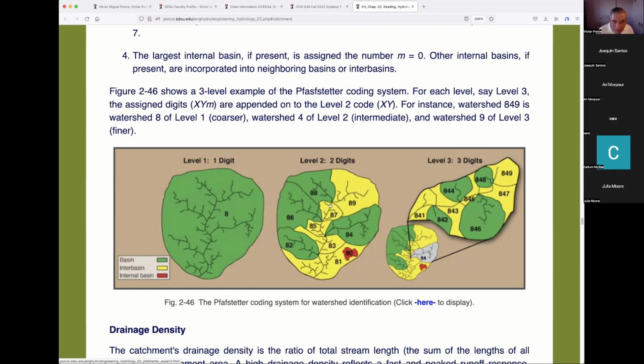Then the intervening reaches of the river are also watersheds. They are kind of lateral watersheds. So he called them the odd watersheds, 81, 83, 85, and 87. And the headwater watershed, that was the 89. And by doing this simple division, he was able to come up with a general classification or general topological description of any watershed. It became very general.